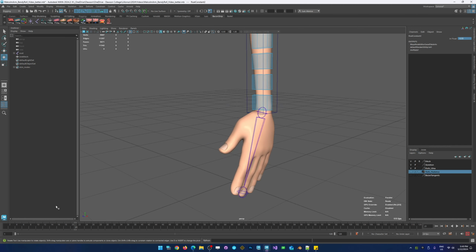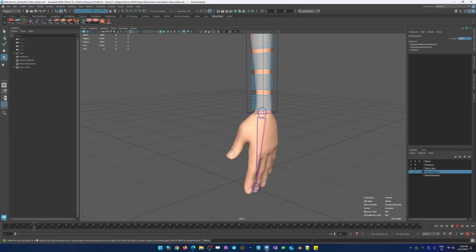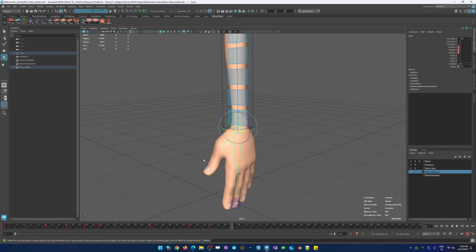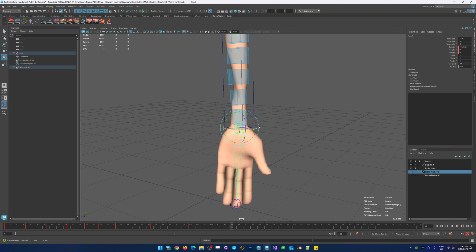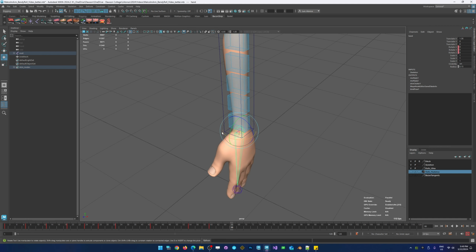All right, so let's look at our result here. We've got this rotation. That's pretty good. There's nothing that's breaking. Now, one of the benefits of this method is that because it's using the X value directly, it's not limited to 180 degrees. If I can actually rotate it more than 100, here, come on, Gizmo. There we go. So it's allowing me to do it, even though I've only got 3 bones to work with. It's still okay. It didn't pop.